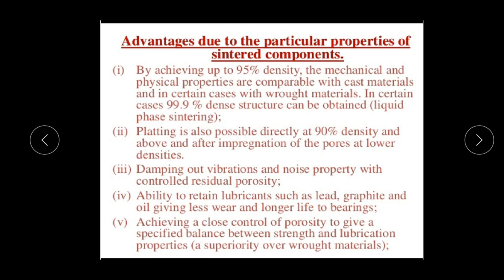Now we will discuss the advantages due to the particular properties of sintered components. Number one, by achieving up to 95% density, the mechanical and physical properties are comparable with cast materials, and in certain cases with wrought materials. In certain cases, a 99.9% dense structure can be obtained.